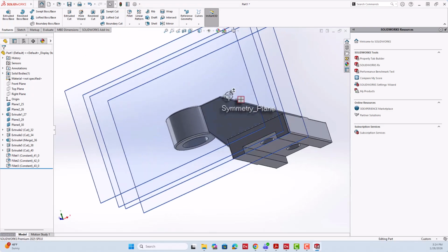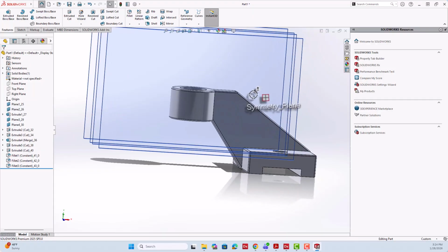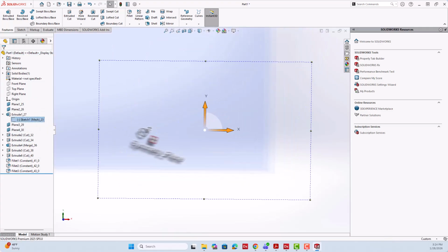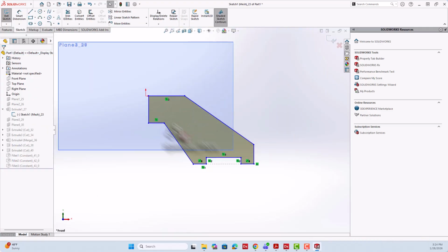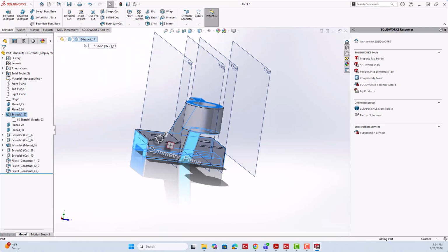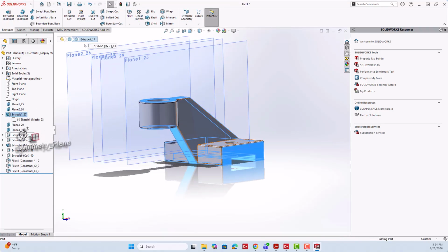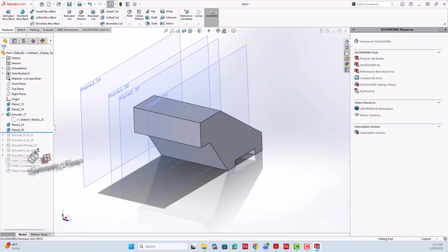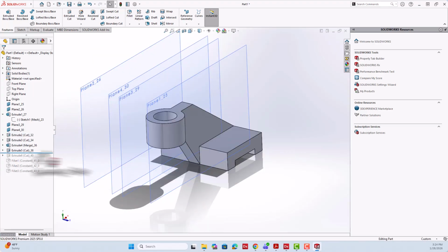So here we have got the entire model history transferred from Geomagic DesignX into SolidWorks. An extrude comes as an extrude. It also contains the basic sketch along with the constraints that we made. The extrude object is transferred as an extrude body. You can roll back in time and check through the progress of this particular model step by step.